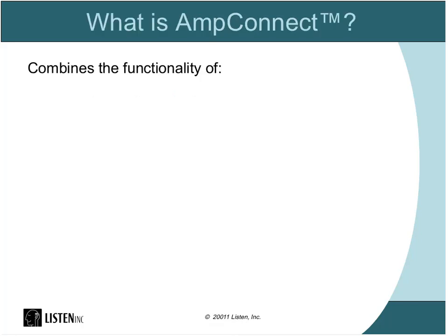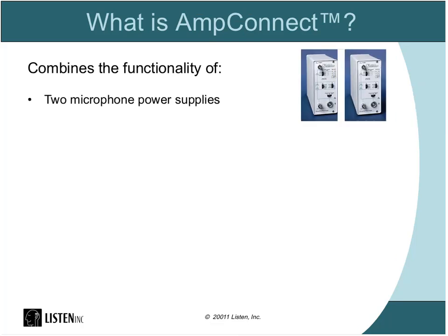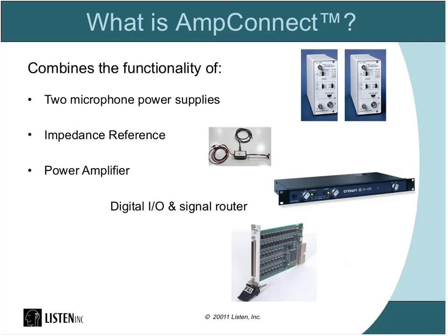So what is AmpConnect? Well, if you're not familiar, it basically combines the functionality of two microphone power supplies, an impedance reference for testing impedance on loudspeakers, along with a power amplifier for sending the stimulus to a DUT speaker or for a mouth simulator. And it also has digital I/O functionality and a signal router.